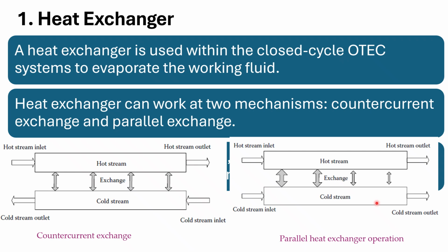To determine the temperature driving force for heat transfer in a heat exchanger, the LMTD is used. It is the logarithmic average of the temperature difference between the hot and the cold streams at each end of the exchanger. So this is how the heat exchanger works.